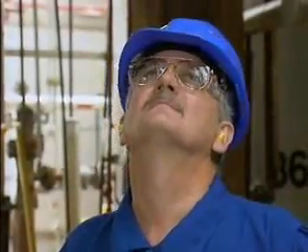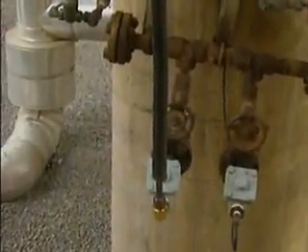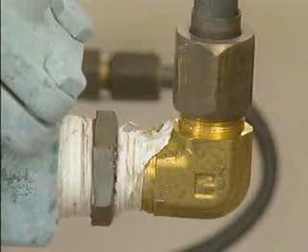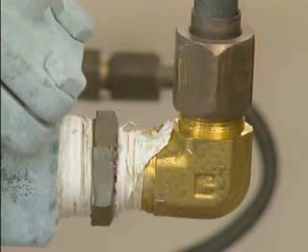Another essential task in a trap station survey is checking pipes for damage and leaks. You should also make sure that the drip line is connected to the lowest point in the steam system. The drip line must be sloped toward the trap to avoid pockets that might cause sluggish condensate flow. The slope also ensures that gravity will keep condensate from building up in the line and causing water hammer. The drip line must also be large enough to carry the volume of condensate that's being produced. It should never be smaller than the trap inlet.